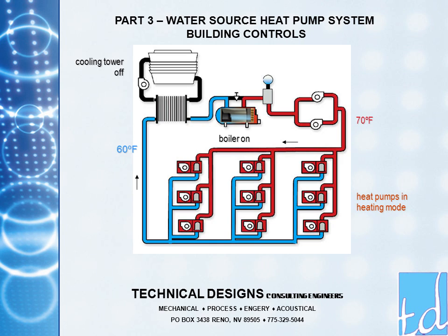Because all heat pumps could start simultaneously when the set point is reset, the boiler must have sufficient capacity to provide heat to all the heat pumps. This could cause the boiler to have larger capacity than needed during normal system operation. One way to reduce the required boiler capacity is to stage units on in an organized fashion. When night setback is used, the boiler is operated to increase the temperature of the water in the loop and to ensure that the morning warm-up can be satisfied.